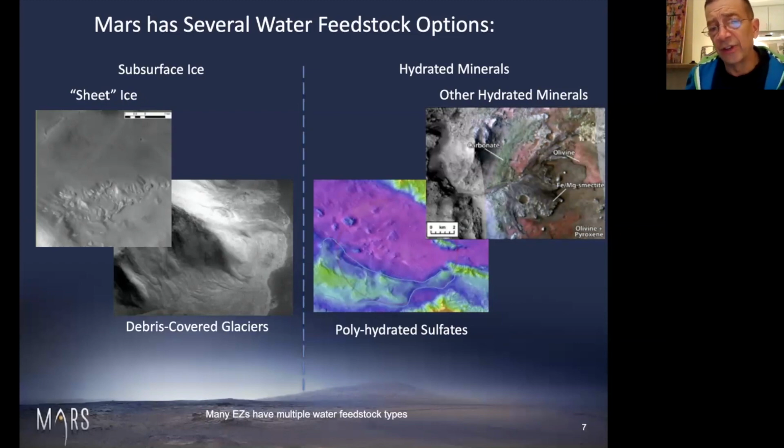And the last challenge that we have to understand is that when it comes to your ride home, we call that a Mars Ascent Vehicle, or MAV. I love that term. But with MAVs, when you launch off a planet, it really helps to be down near the equator. That's why we have launch sites at Cape Canaveral and French Guiana, and anyone who's trying to do it often tries to be down at the equator, because the spin of the planet helps you with your launch and saves a lot of propellant. When you go up further north, that doesn't help you so much, and so it could potentially impact our ability to come home.